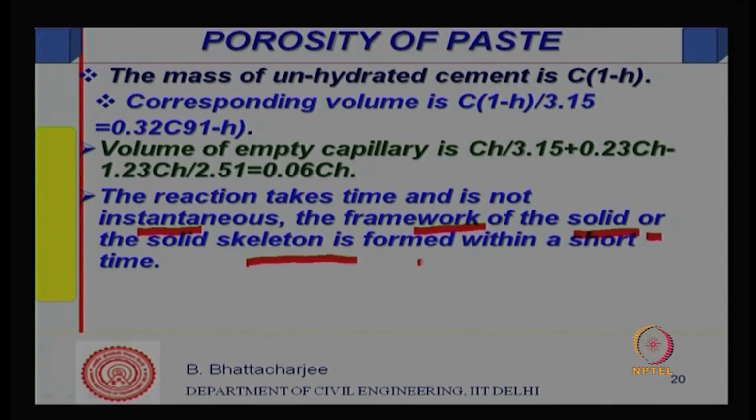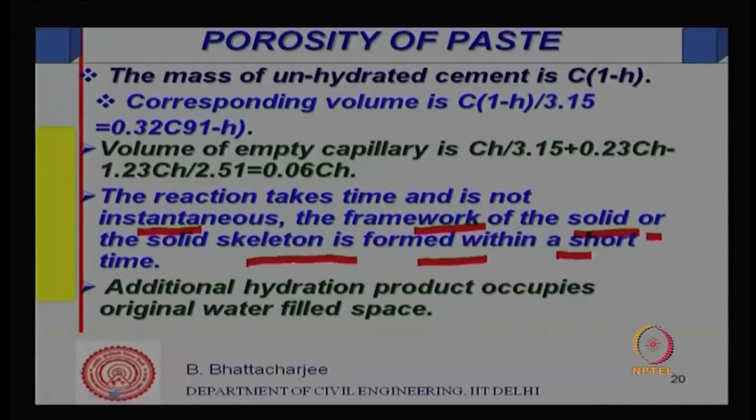So, the solid skeleton is formed within a short time. Since the solid skeleton is formed within a short time, the rest of the hydration product occupies only the space available within that solid skeleton. So, additional hydration product occupies the original water filled space within the skeleton.